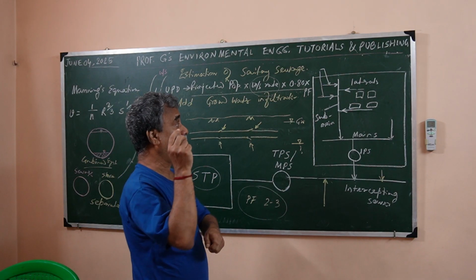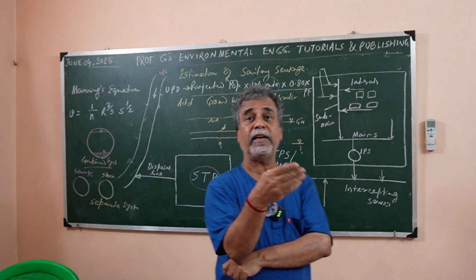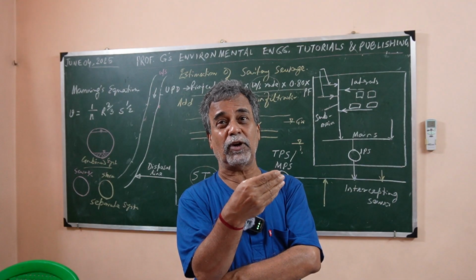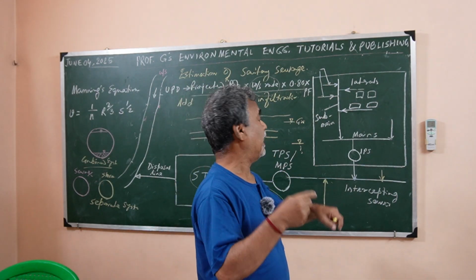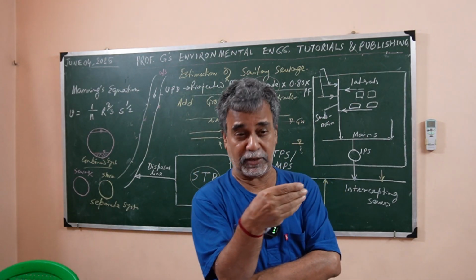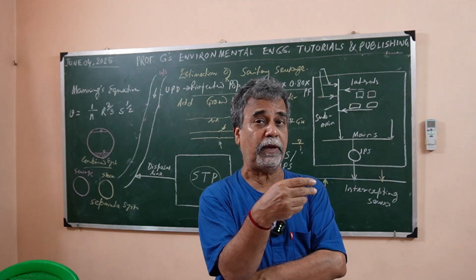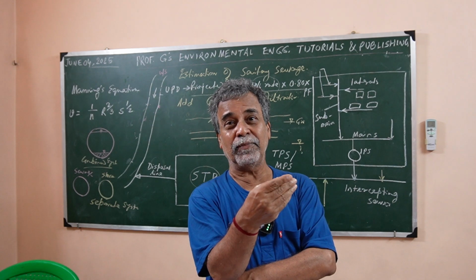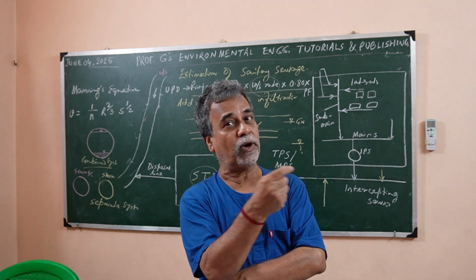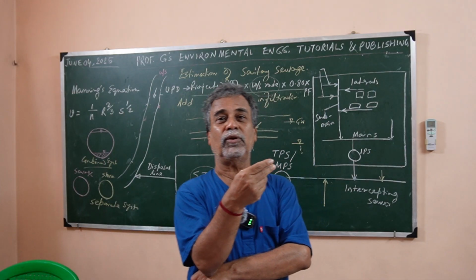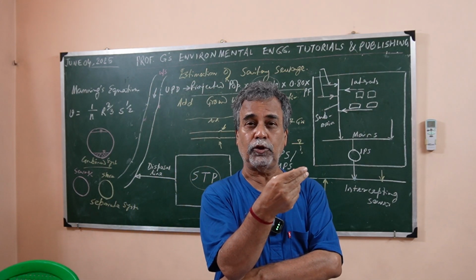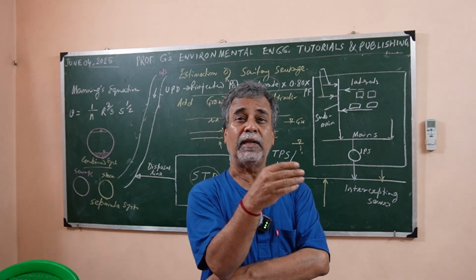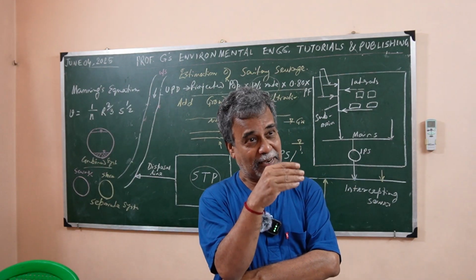But remember that with modern construction aids, the minimum quality and standards of workmanship in laying the pipeline could be maintained. But that does not mean that there is any relaxation for the water tightness of the sewerage system. In no case is relaxation to be permitted. So the water tightness test as per the IS code or CPHEEO manual has to be conducted and complied with,